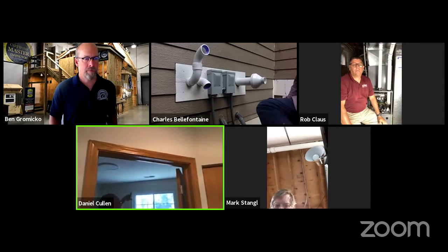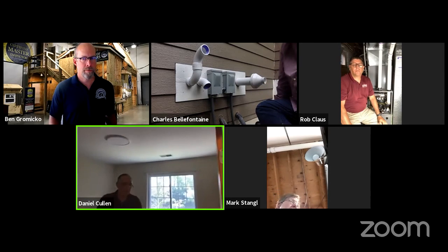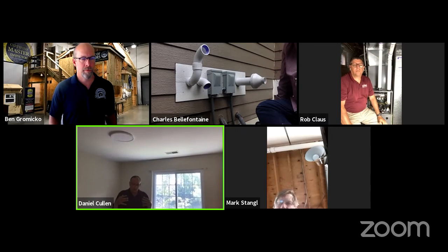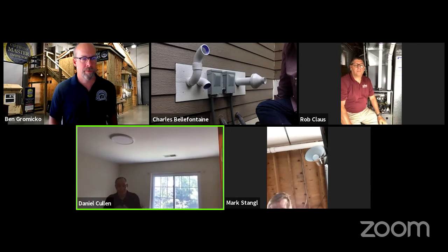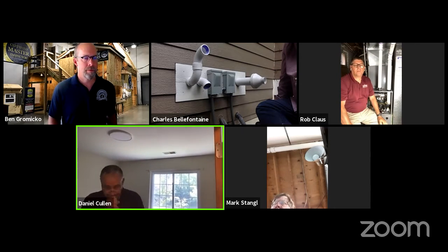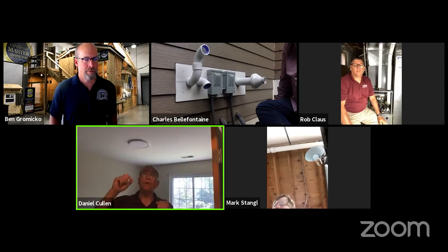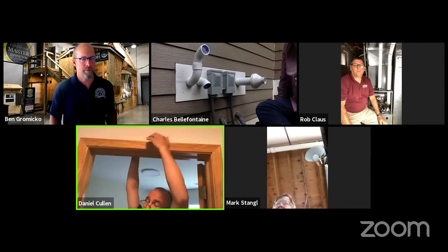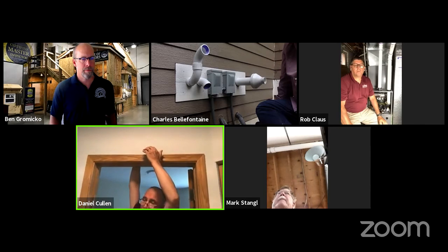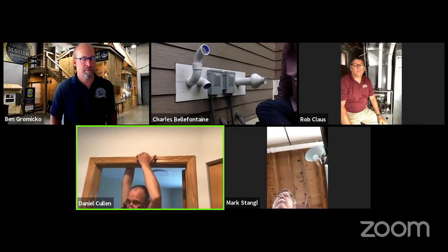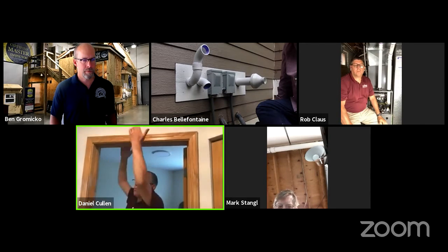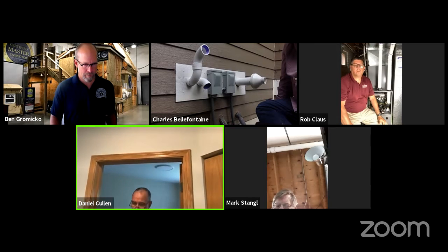We have a supply, but no return. So it's a really good thing to have return air in every separate habitable room. So what I will do, again, we just moved in here last fall, is put transfer grills here over the door, one low, one high, to muffle the sound a little bit.